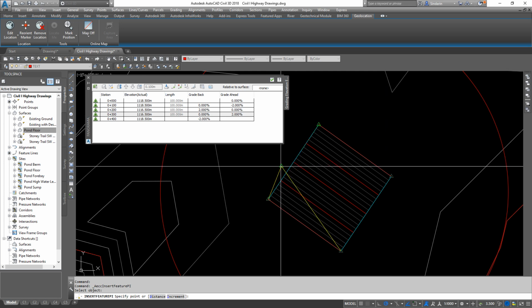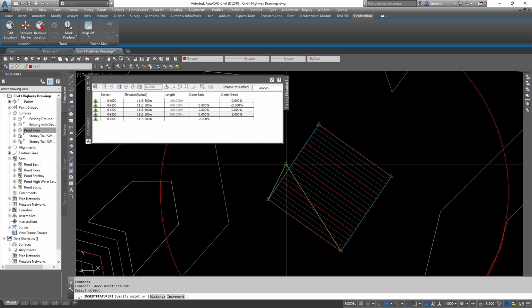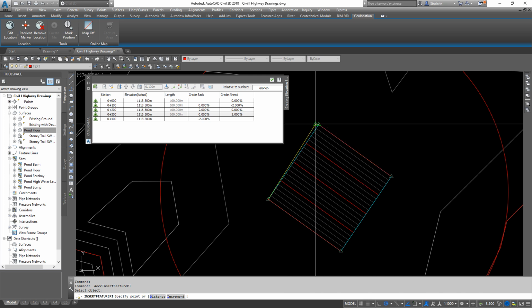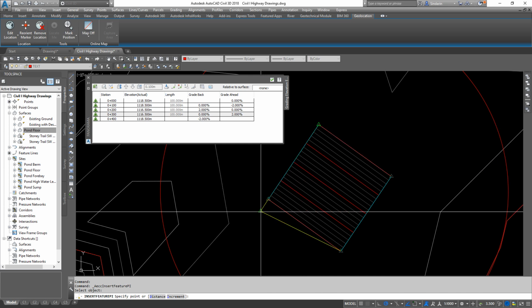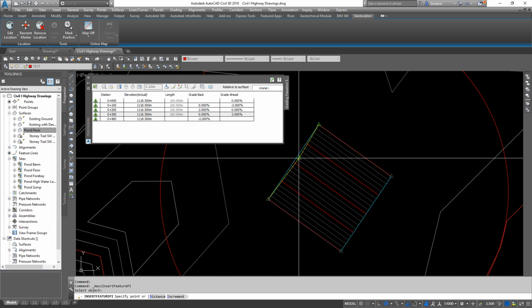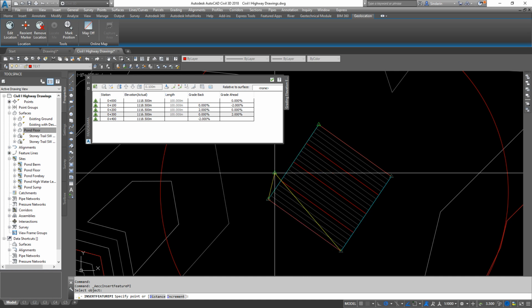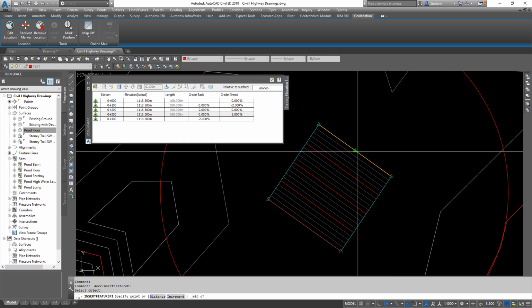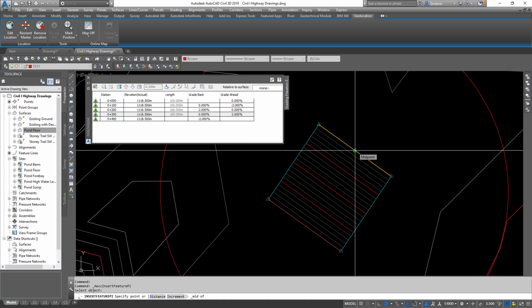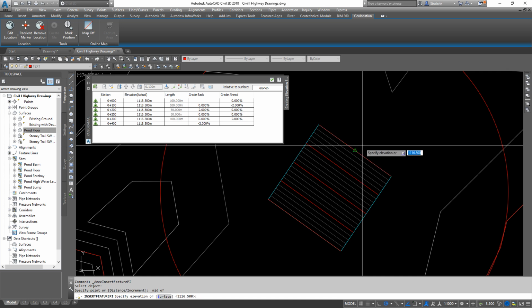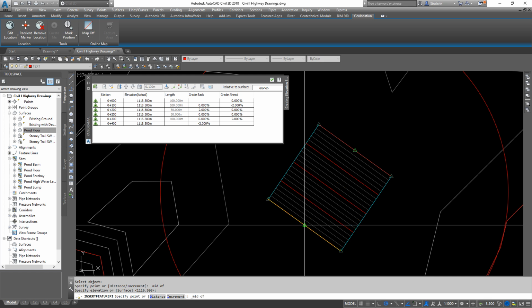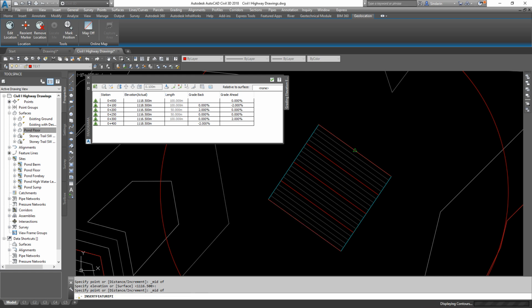Now you may get a display issue where this happens. So even though I'm hovering here, it's connecting to the bottom right. If I click, it's still going to triangulate with this one. So that is not an overly large deal. Just click here, it'll still insert a proper one. But the first one I'm going to insert is in the midpoint right here. Specify my elevation. I'm just going to accept the default, hit enter. The second one I'm going to add is on this end. Select the midpoint,